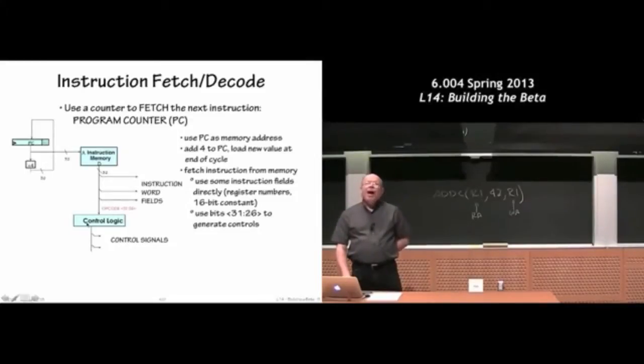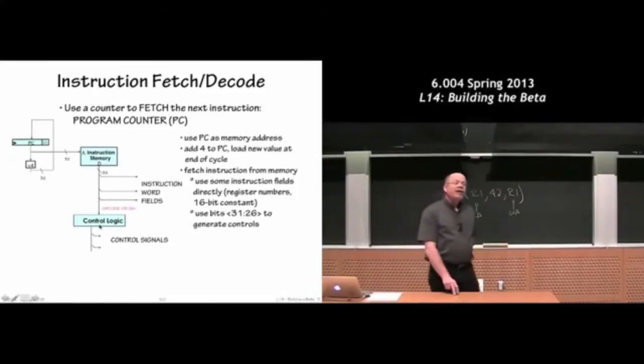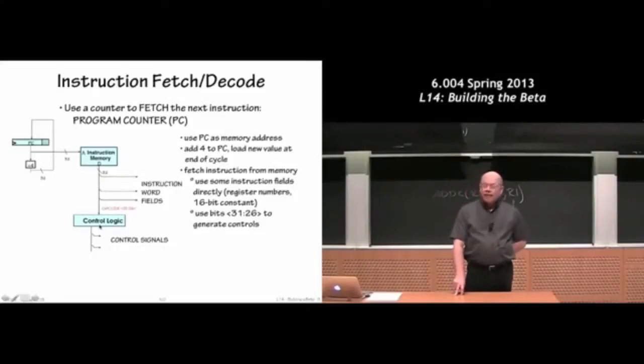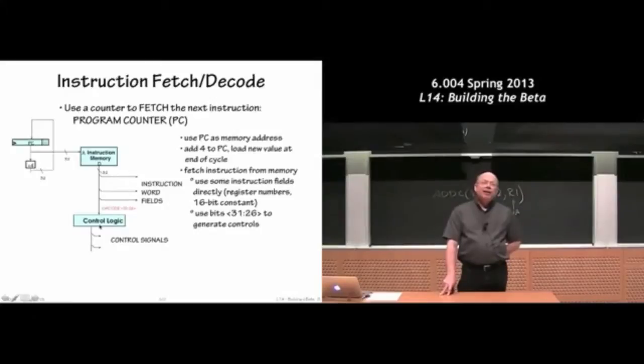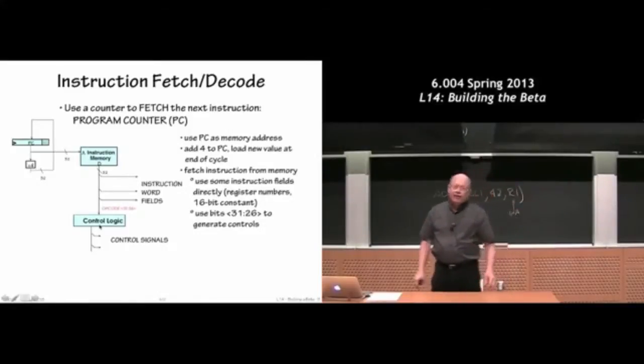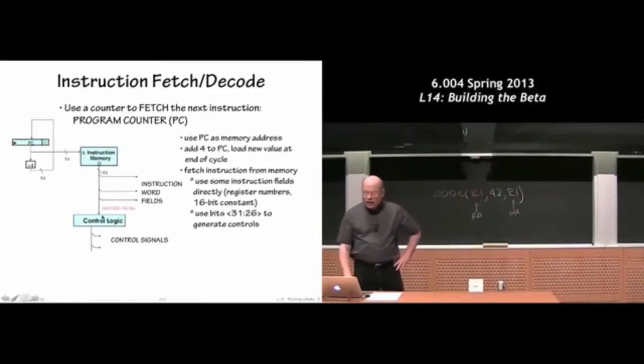However, we will take the 6-bit opcode and run it through this control logic, which you can think of as just a big read-only memory. At least in this diagram, it would have 64 locations because we send in 6 bits, and with 6 bits of information there are 64 combinations. So depending on which of the 64 opcodes goes into here, we're going to develop a set of control signals.